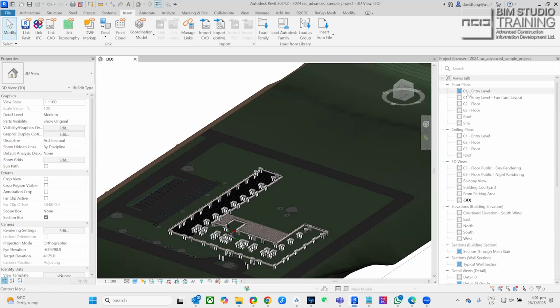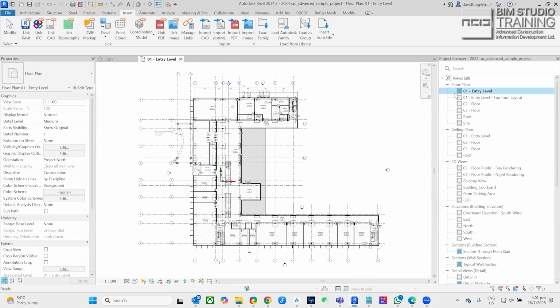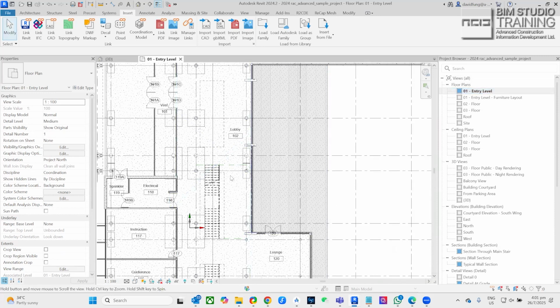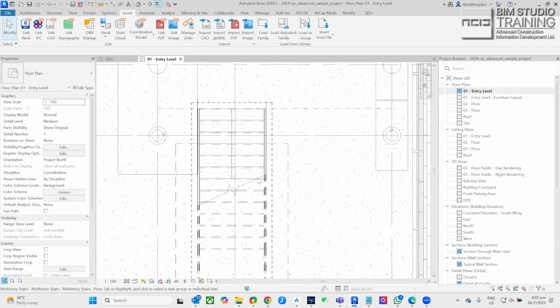Now, if you look back in the floor plan, I asked you to look at 4 things. Now look at grid line E. Now it looks different. On grid line E, you have 2 circles. That means I have 300 columns from the architect, and then after the structural engineer did the calculation, it is not enough. It will collapse. So he built a bigger column. So what is the size of the bigger column? What is the size? 450.